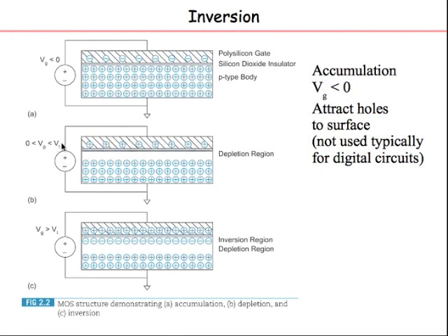If you notice here, there is another parameter called Vt. This is again a very important parameter, Vt, the threshold voltage of the transistor. We can think of the threshold voltage as that voltage at which you have strong inversion happening, where the concentration of the free carriers is the same as the acceptor ion concentration.